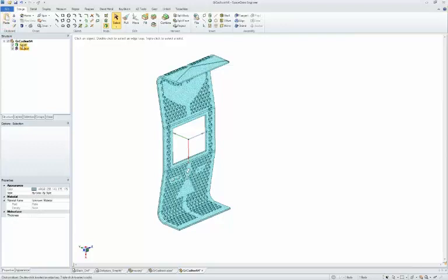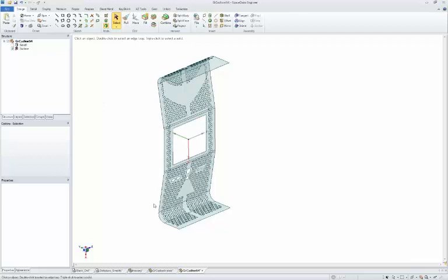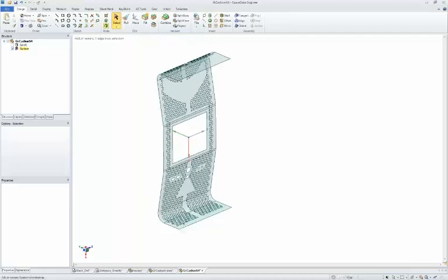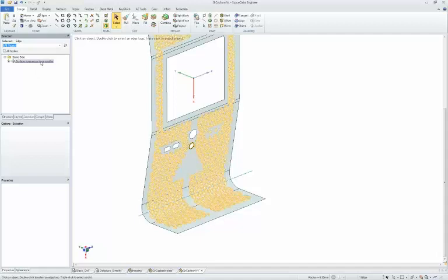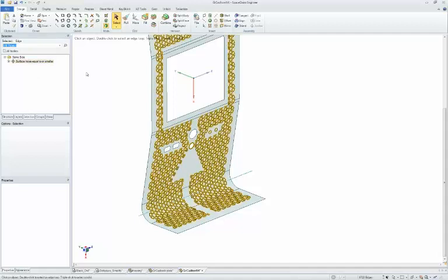Now you'll notice what I have is, instead of a thick solid, I have a thin surface body. And sometimes people will do that just to get a thin body for analysis. But what I have now is going to be faster to simplify and remove things on, because that handy search tool that I've been talking about this whole time will just grab surface holes. So these are any holes that are smaller than this initial circle I selected. And if you look in the bottom right-hand corner of my screen, that's 6,700 edges that I'm getting rid of